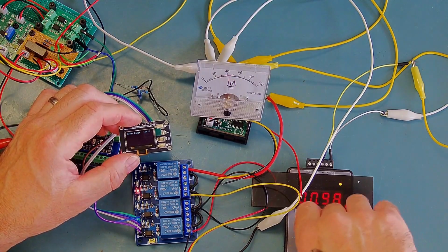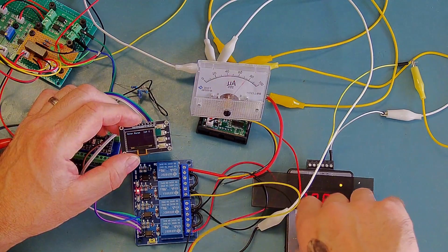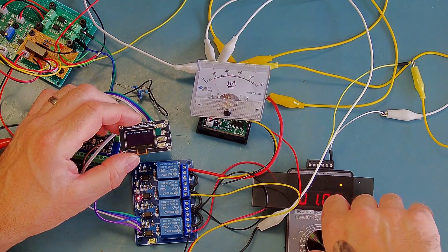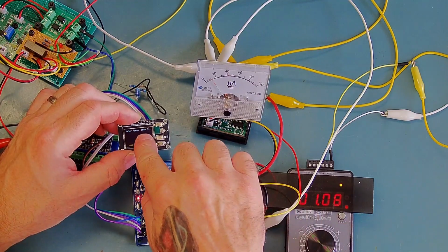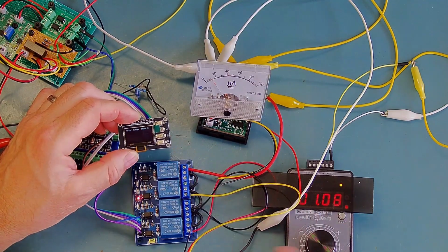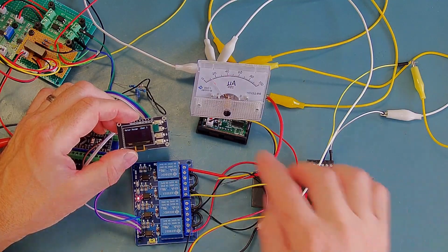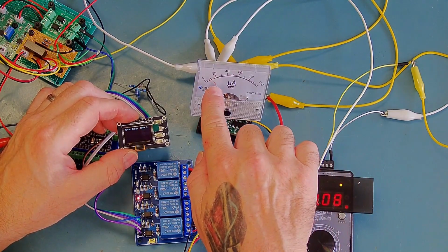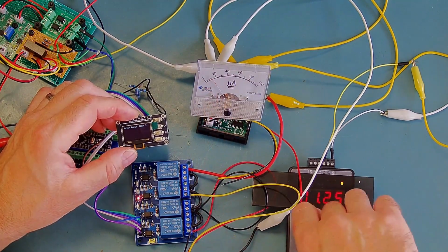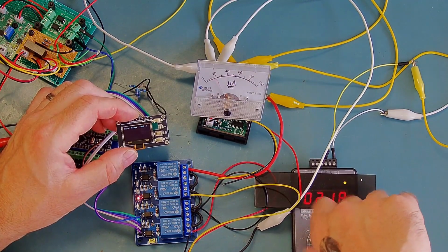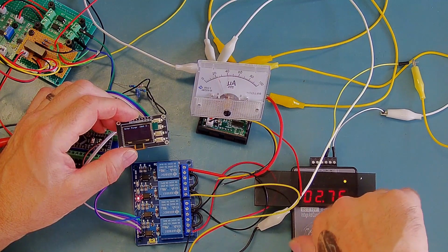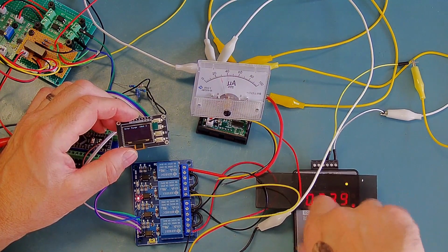Okay, so we go up to the 1 milliamp range, and we'll continue to go all the way through the range until it trips onto the next one. Okay, so now we're on the 10 milliamp range on the meter. We've got just over 1 milliamp on the meter, and then we'll go up here, so we need to go past 10 milliamps now for this to go over range again,